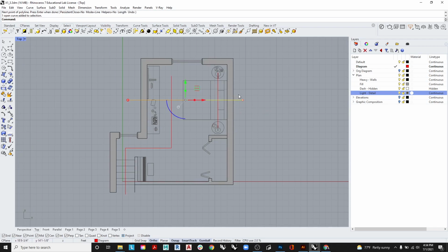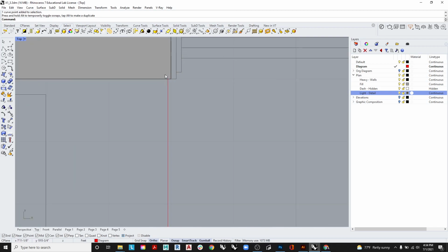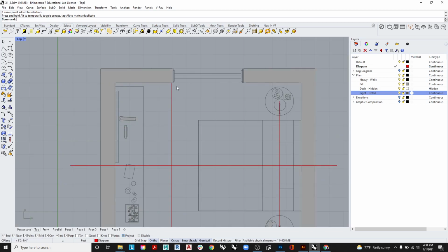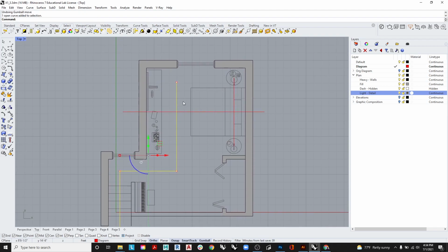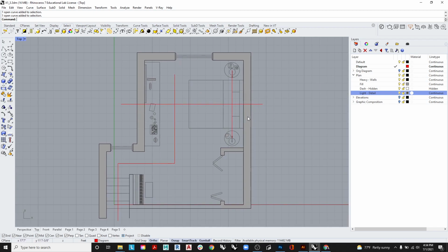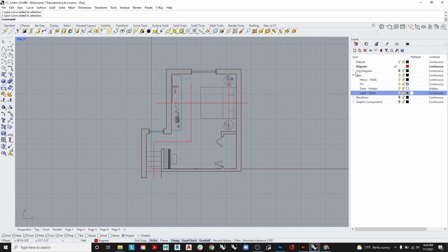I would say the lines that are showing like an axis of symmetry or a circulation line, it's best to not have them die directly at a point, because this kind of overlap or having the points meet at the same line will make it look like this is the line in the space. Stopping short of it will indicate that maybe we're indicating something else. Or an axis of symmetry, you could pull outside of the walls so that it's not aligning with the edges of the existing walls. So those are a few you can take a look at.